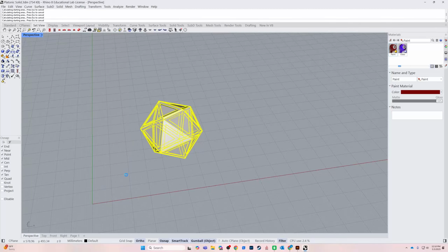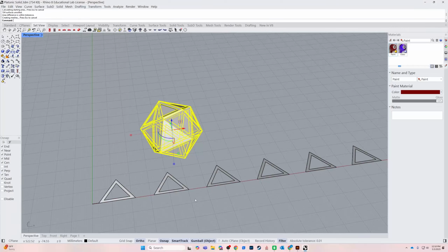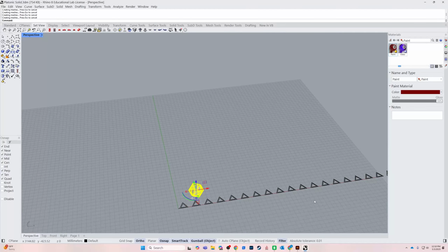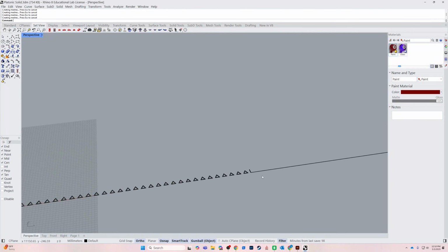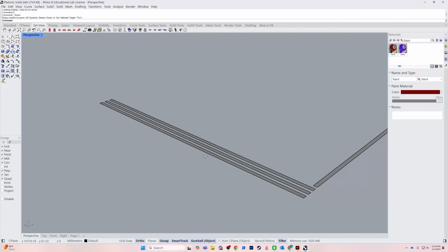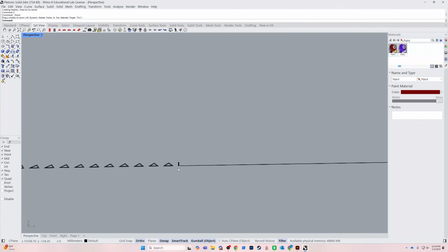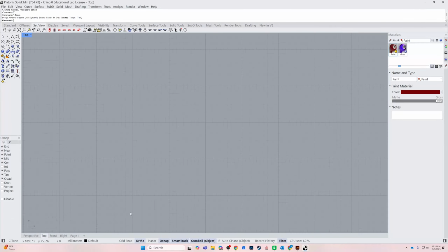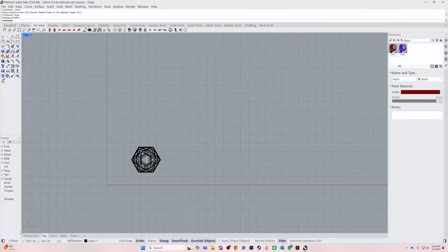And what you'll see is there's going to be 40 triangles, and all of the sides of the triangles will also appear, which is way too much information, because this is also including the front and back and sides, these little 3mm thickness of the wood sides here, which we do not need. So we've got to prep it a slightly different way. I'm going to go ahead and press Control Z to undo.